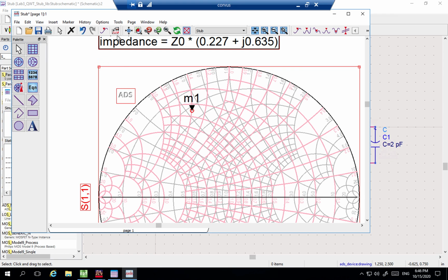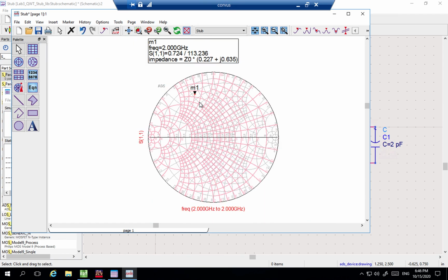All right, so I'm just going to do a full screen here. Right now we need to move this around the Smith chart so that it lies on the 1 circle for the admittance. So you see the circle here, this is the 1 circle for the admittance. If you guys have done this in class in 3909, you would have had the impedance and then you would have transferred it to admittance, if you remember, because we only had the impedance Smith chart. But right now we have an impedance and an admittance, so we can simply move a certain distance away from the load, so that the input admittance is lying on the unity circle, and then the imaginary part we can cancel out with the stub.